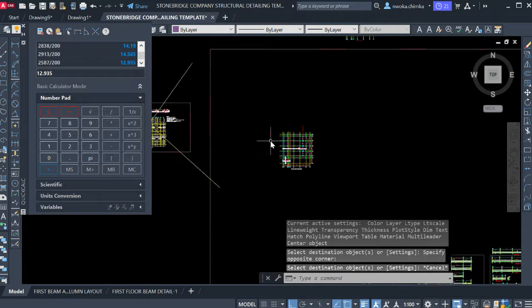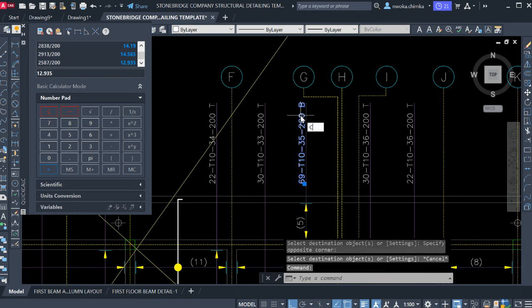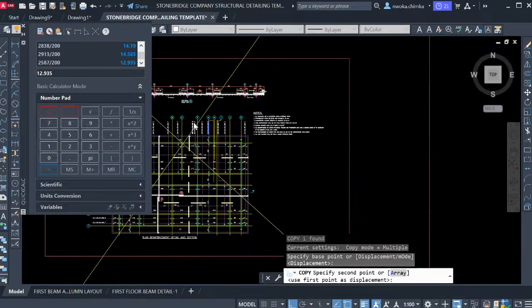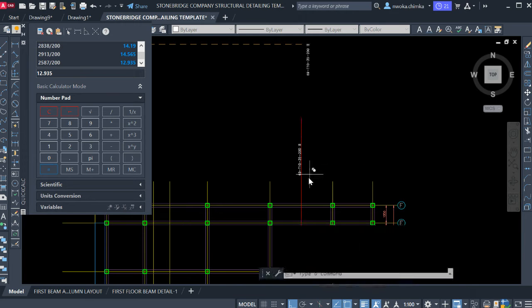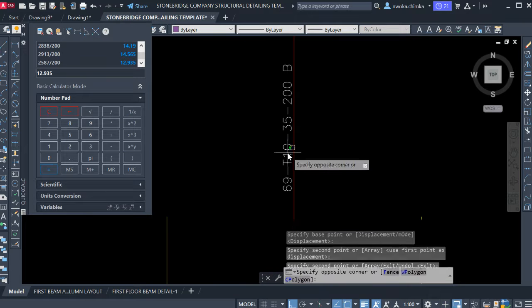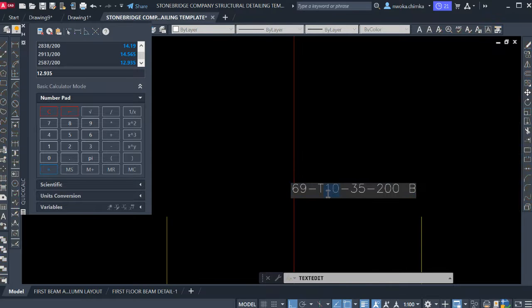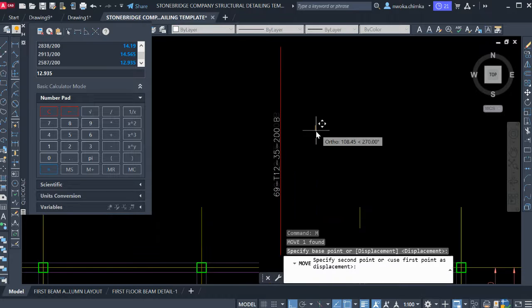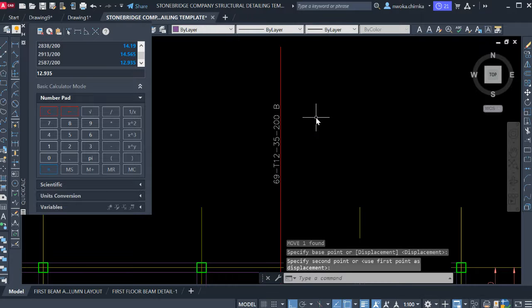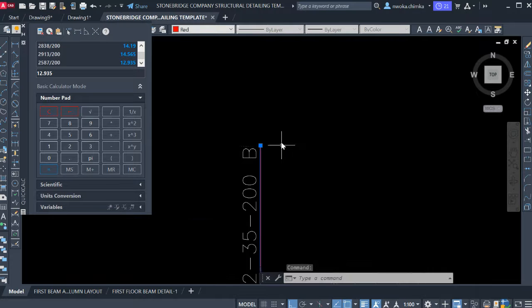Okay, so right now we go to this place to copy one. Since we are dealing with a bottom bar, we just copy a bottom bar, and the size of our reinforcement is 12. So we go here and change the slab reinforcement first to 12. Okay, so put this to 12, and then we just bring this down a bit again, small, on the upper floor. Okay, and then we just click this and do this.